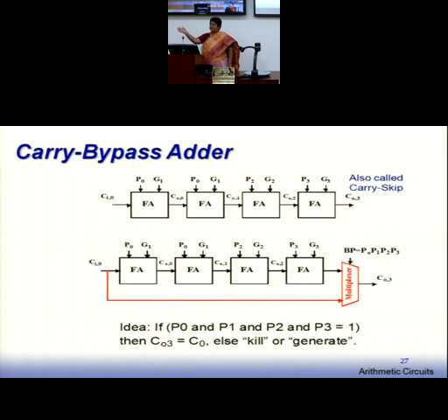Do not wait for carry out to come from every bit position. It's called a skip. You skip the entire 4 block. Just look at the generate functions. If all are 1, add them together and simply have that come at the output. Simple. 4 blocks taken together.